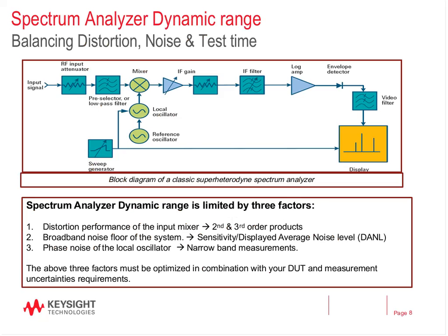So this brings me back to spectrum analysis. One of the first tools you usually go to look at and analyze your spurs is a spectrum analyzer. And if you're familiar with the basics of spectrum analysis, you basically have a very similar receive chain on your spectrum analyzer as you do in your device under test.